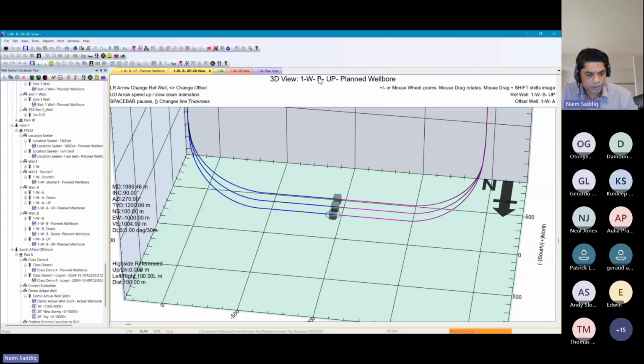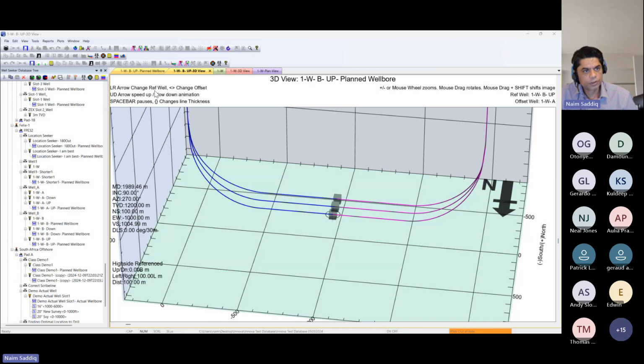So I will show you maybe, because we are running out a little bit of time, but I wanted to also show you something else about the hydraulics. Suppose you have come up with a design. You can see on my right-hand side, you have a casing structure. This is 13 5/8" casing, and then everything is a liner. When you drill this final section, 6 1/8", what happens to the hole cleaning?